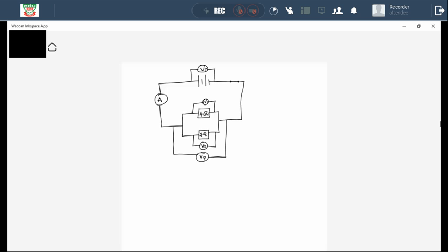So when current flows via the ammeter there from the positive terminal, when it gets to the point where the two pathways separate, current there is going to divide. But how is it going to divide? The pathway that has got more resistance, the 4 ohm pathway, it is going to get less current. And the 2 ohm pathway, it is going to get more current because current and resistance are inversely proportional, right?